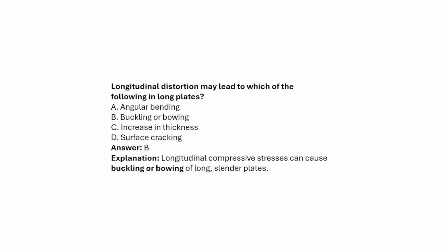Okay. Longitudinal distortion may lead to which of the following in long plates? Option A, angular bending. B, buckling or bowing. C, increasing the thickness. D, surface cracking. Answer will be B. Longitudinal compressive stresses can cause buckling in long slender plates. Okay.